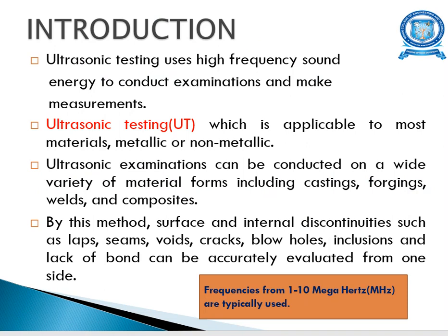Ultrasonic examination can be conducted on a variety of materials, including castings, forgings, welds, and composites. By this method, even surface and internal discontinuities such as laps, seams, voids, cracks, blowholes, inclusions, and lack of bond can be accurately evaluated from one side.